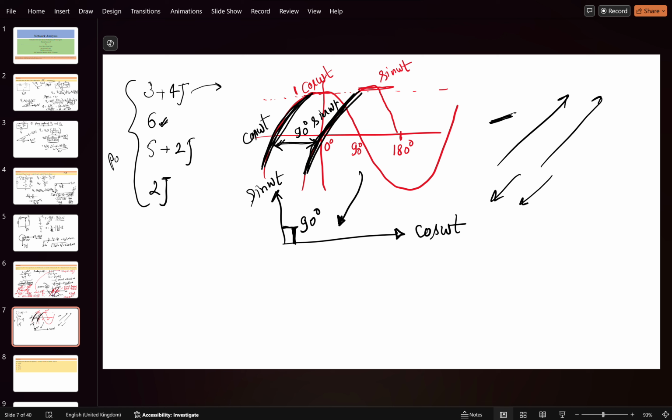You can represent this in terms of phasor. Okay. Magnitude, because you cannot represent cos omega t here, so directly we represent in terms of magnitude. Suppose the cos omega t magnitude was 1 here. I have represented it here. Sine omega t magnitude we have already considered 1. So what will the net value? Net value will lie here somewhere. It was 1 square plus 1 square plus 2 times of 1 multiplied by 1 cos of 90 degree. Cos 90 will be 0. It will come out to be 2. So this angle will be 45 degree because it is the same. So this came out to be root 2 angle of 45 degree, the net value.